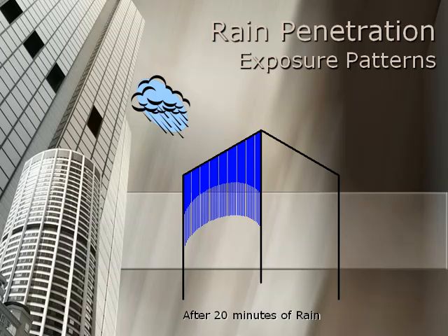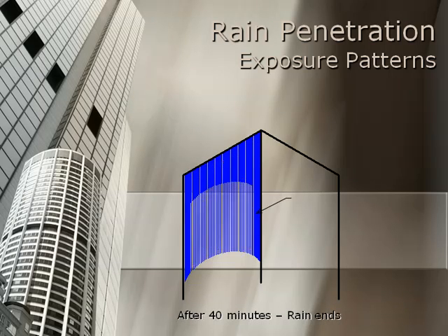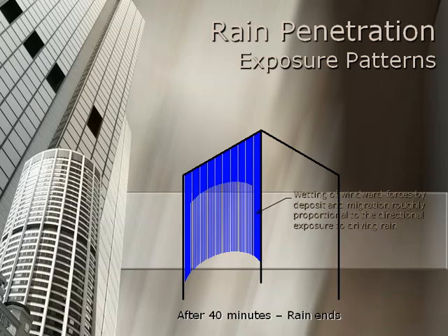As wind parts to flow around and over a building, a cushion of high pressure but relatively still air is created at the center of the wall. This dead spot protects this area of the wall from rain. Wind accelerates around the side and top edges of the building, driving rain more forcefully against these parts of the wall. Studies have shown that these edges can receive more than 20 and as much as 50 times the amount of rain than the center of the wall. This discrepancy in wetting intensity is greater with taller and narrower buildings.